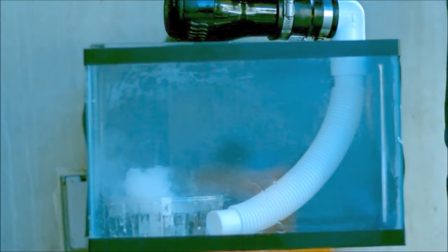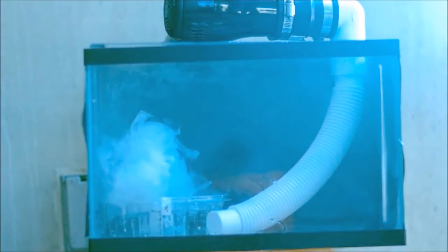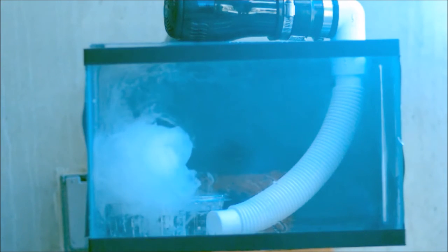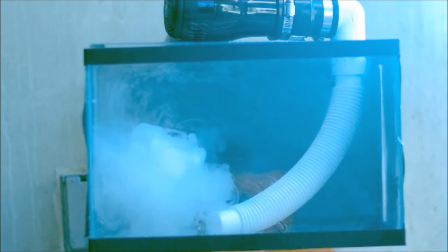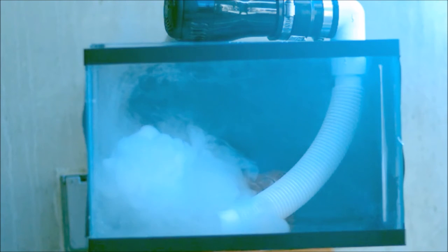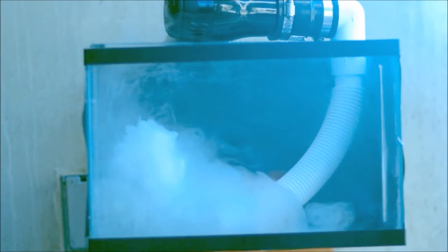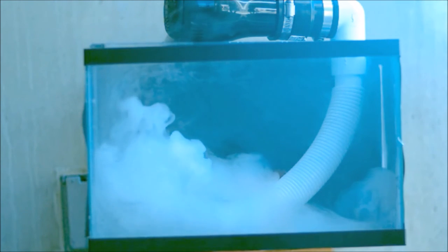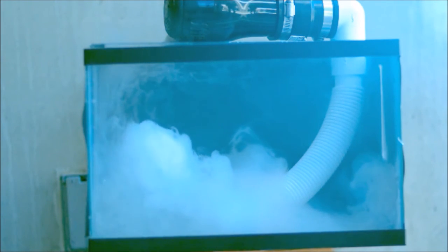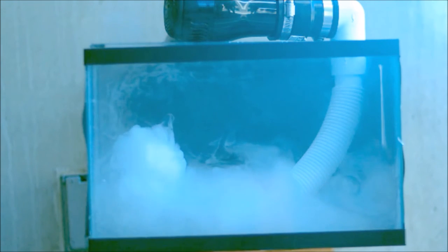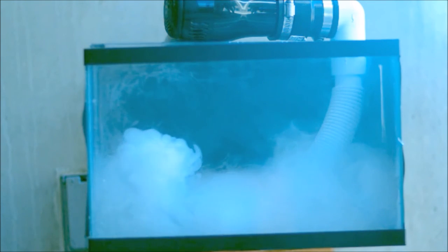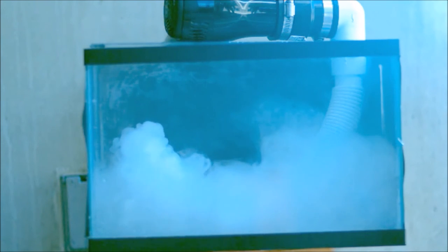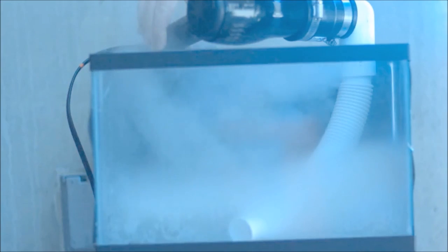This plexiglass cube is presented in this video to simulate a workspace without adequate ventilation. Now, many construction chemical reactions may be colorless and impossible to see with the naked eye, such as paint strippers. For that reason, a dry ice and water mixture is used here to create a fog that fills the space inside the plexiglass box. The fog you are seeing in this video is a chemical reaction that occurs when dry ice contacts water. This mixture and reaction was selected so you could actually see how chemical vapor concentrations can be decreased by applying forced air ventilation to a simulated workspace.